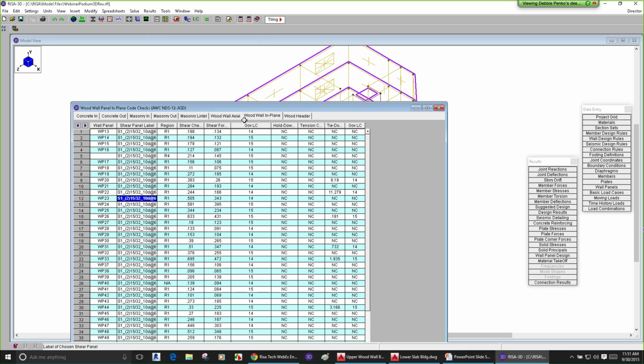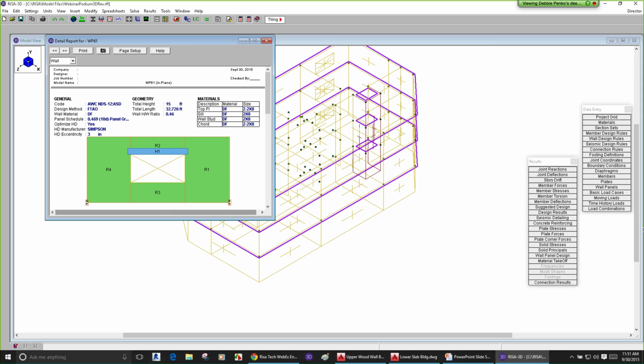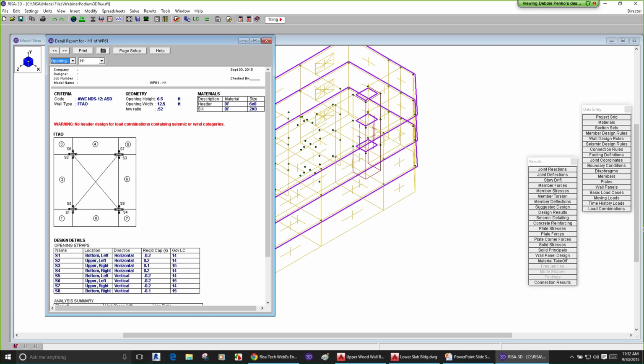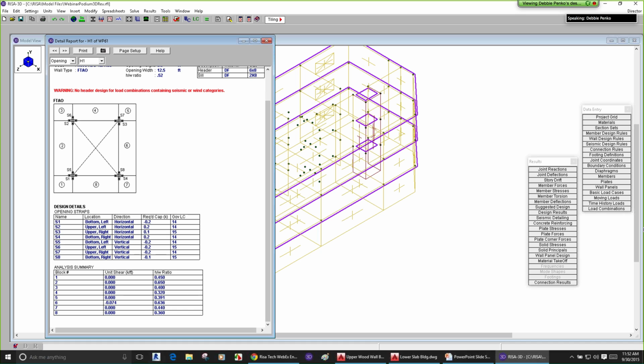I've also got a different example here. So if we look at, for the example, I did a force transfer around openings on the upper wall here. So that helps us calculate the force around each opening. And so we'll see inside of the opening report, it gives us the forces. It breaks the wall into segments. Each different piece transfers the force at each little piece. So you see 1, 2, 3, breaking it all the way to 8, and inside of that, what the force is calculated across that, and then the analysis requirements for that.